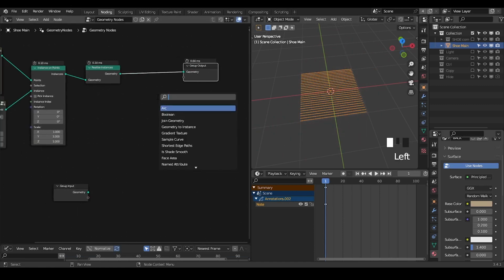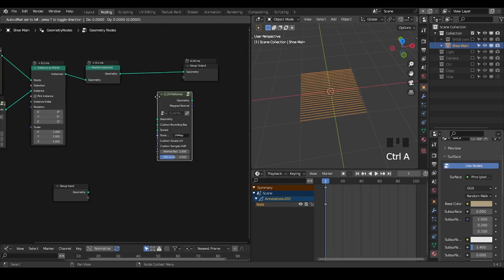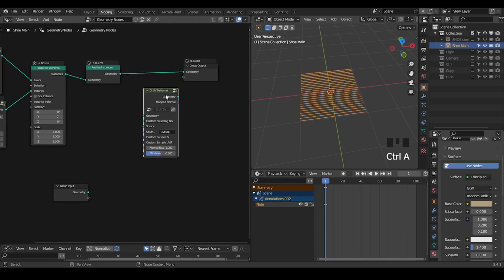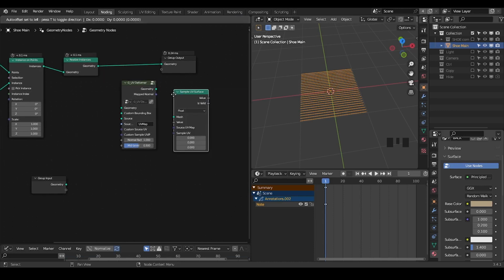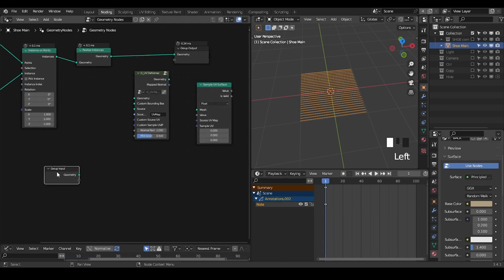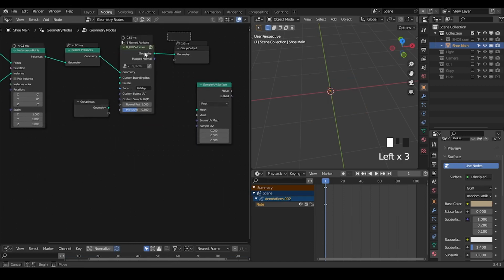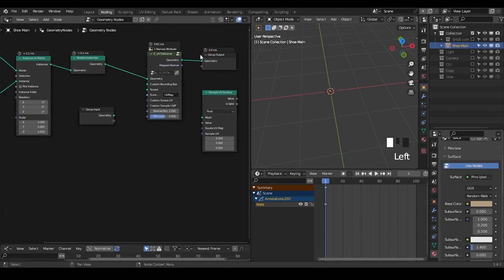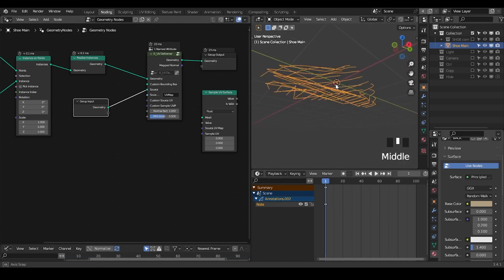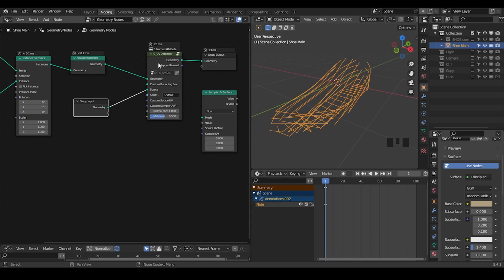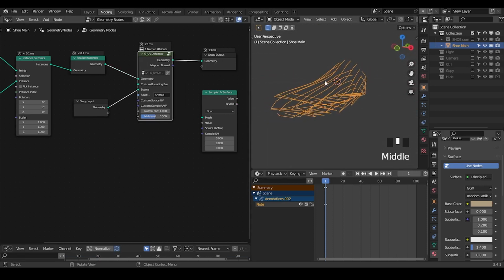Then we're going to use the preset called UV Deformer. I've discussed this preset and I even discussed how to build it. Basically, the whole idea is to use this sample UV surface, and if I directly plug that to the geometry, there is nothing because we need a source to evaluate. So let's plug the geometry into the source. Immediately we can already see some deformation of the curves, resulting in a shoe shape.